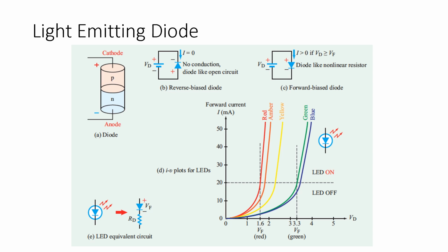A 2-volt power supply on this chart means I'm going to easily be able to light up the reds and the ambers because their forward voltage is around 1.6. I'm probably even going to have to put a resistor in front of them to drop it down a little bit. But with the yellow one, that's around 2, and see the curve there, it's not a perfect linear relationship. So at 2, we might get a little faint yellow glowing.